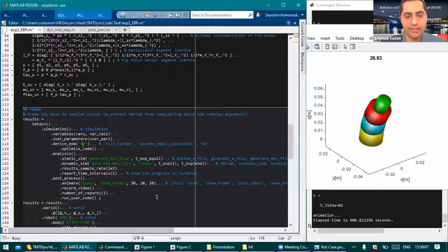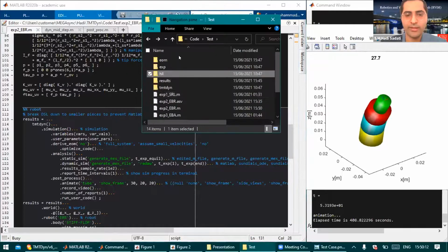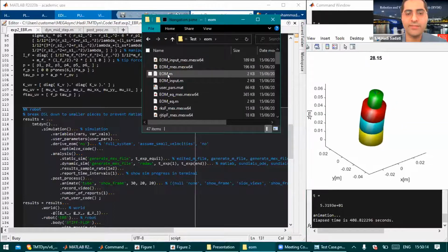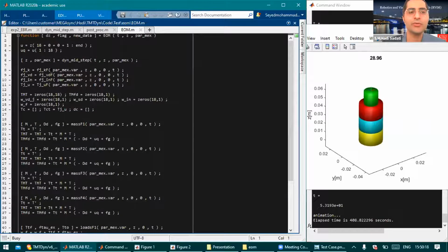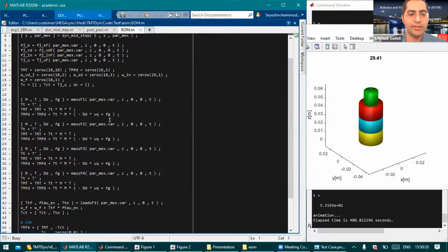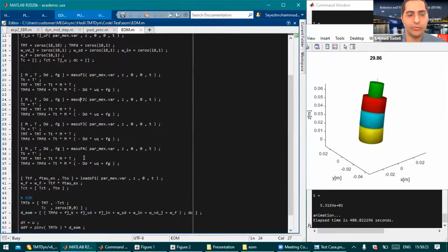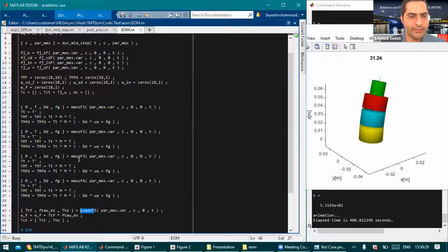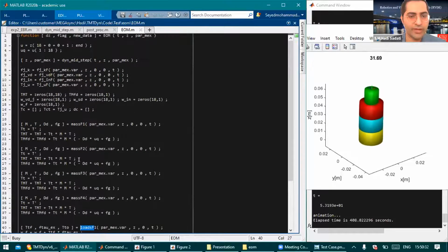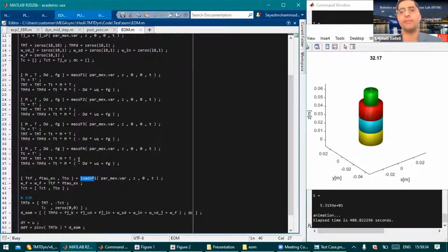Also, let's have a look at the equation of motion folder. There is a file eom.m here, and if I have a look, this is actually the derived equation of motion. You see different inertial terms associated with the masses, and the load for the external load. And in this specific derivation, we don't have any specific beam, but you would see other elements here as well.